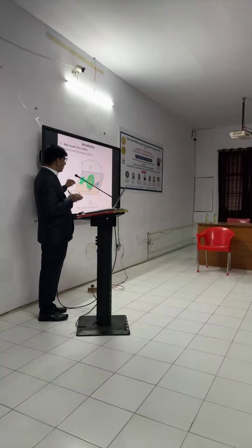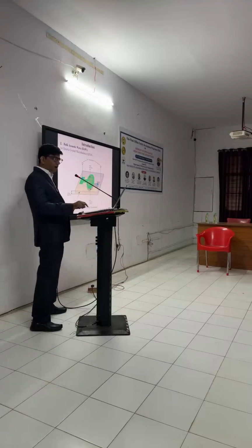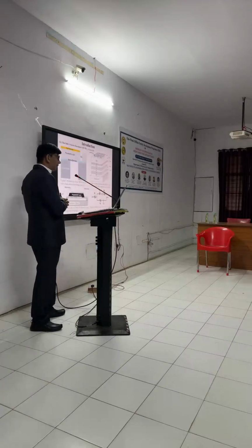What is in our control? We can deposit this top and bottom electrode, but that will not decide our resonance frequency. But who will decide? This quartz substrate thickness only. Clear? So now we will move to another device, that is the FBAR.